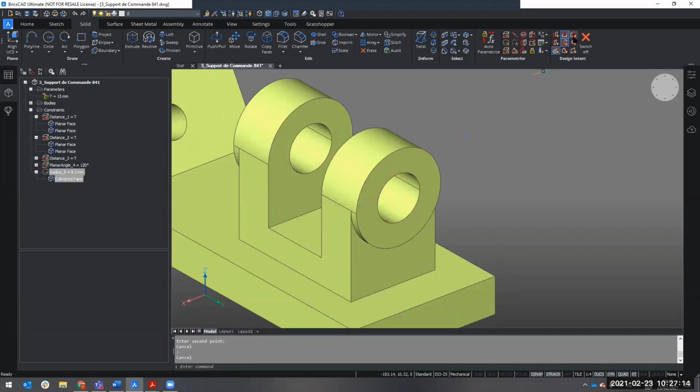And to do that, I also wanted to come along with this outer cylindrical surface. You can do that by putting on the coaxial surfaces design intent. And if you now redo that exercise, which I just did, you can enter a base point, for example, locking even the dynamic UCS with shift.